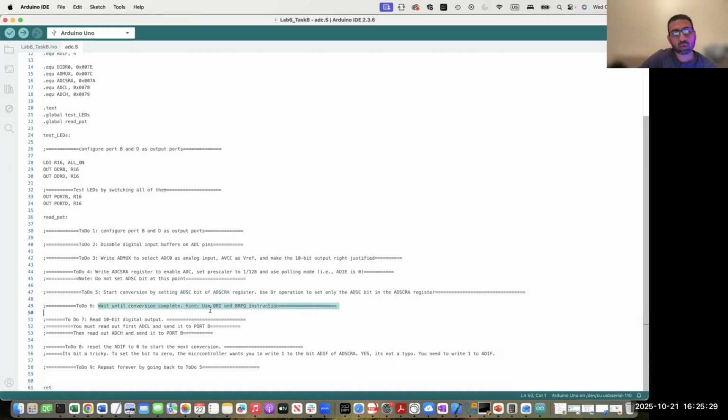Then the next TODO is to wait until the conversion is complete. And how do you know that the conversion is complete? You continuously monitor the value of the ADIF bit in the ADCSRA register.